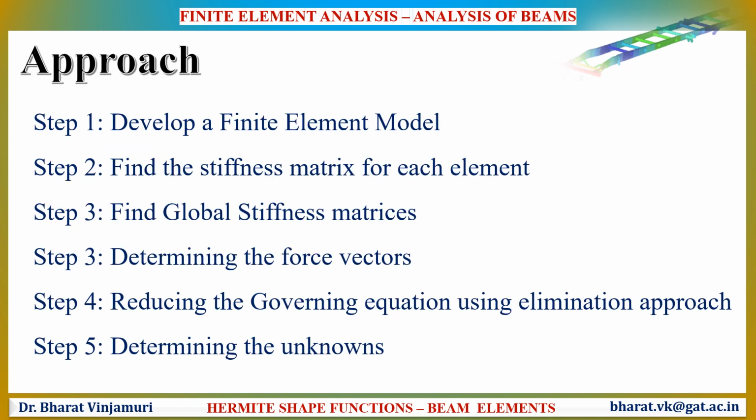The following approach is followed while finding the deflection. Initially, from the given geometric model, a finite element model will be developed. The stiffness matrix of individual element will be determined, and later the global stiffness matrix will be determined for the entire structure. Once the stiffness matrix is determined, the force vectors will be found and the governing equations will be reduced by using the elimination approach. Finally, the unknowns will be determined.